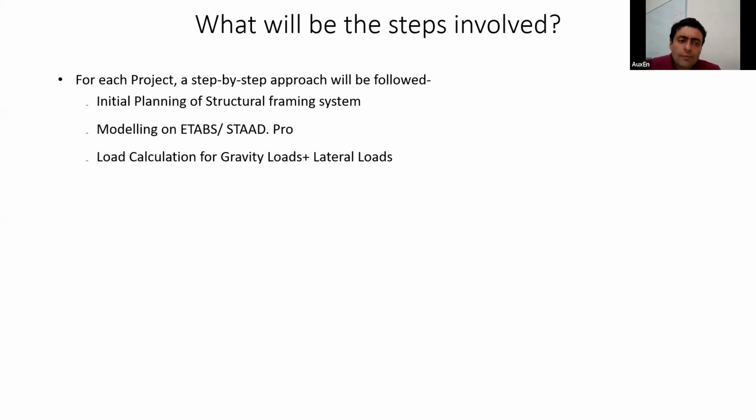Then we will do an extremely important step, that is the load calculation for gravity loads and lateral loads. For all the projects, we will be doing a detailed calculation for gravity loads and lateral loads. For this, we may have to use different Indian standards: for wind loads, earthquake loads, and also for roads and bridges. Whatever is required, we will be using that.